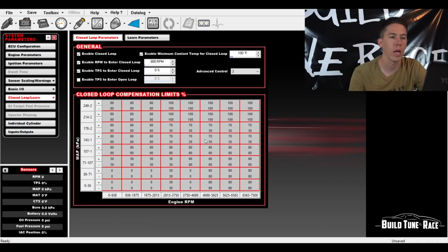I've been really debating, and I'm going to here soon, adjusting anywhere that I know is tuned incorrectly to only allow like a 10 to 20% change. That's a double-edged sword. I've looked at a Copo Camaro before, and they allow 10% over the whole fuel map. 10 to 20 isn't bad. If it goes 20% lean, though, that could be dangerous.